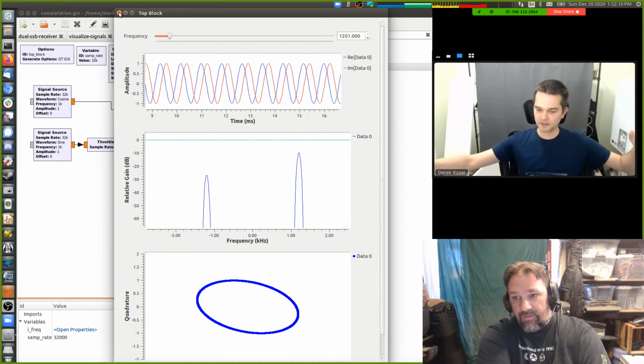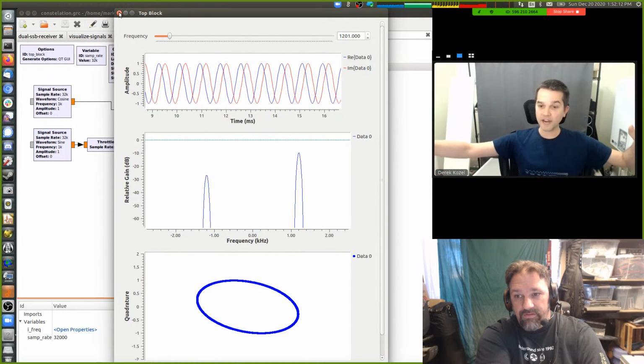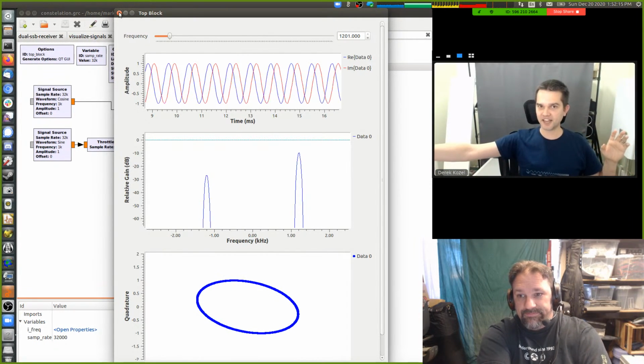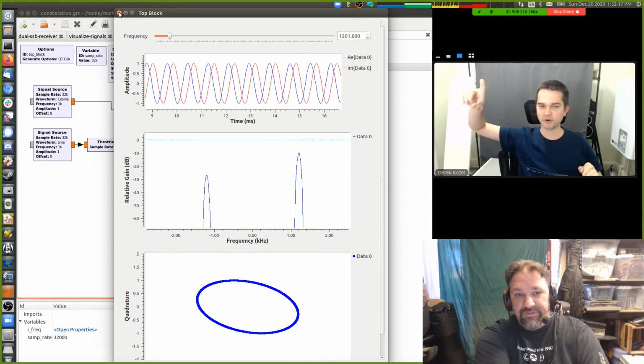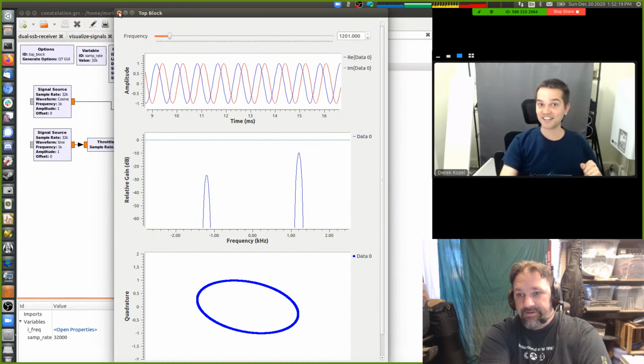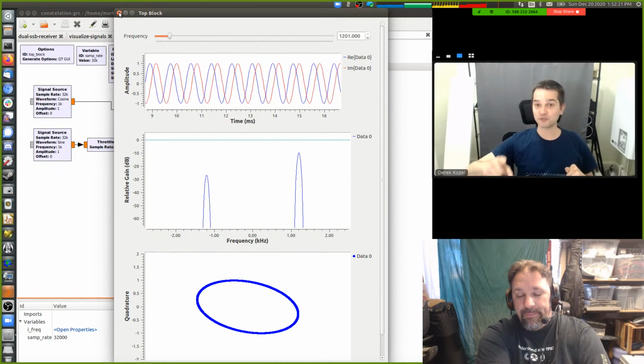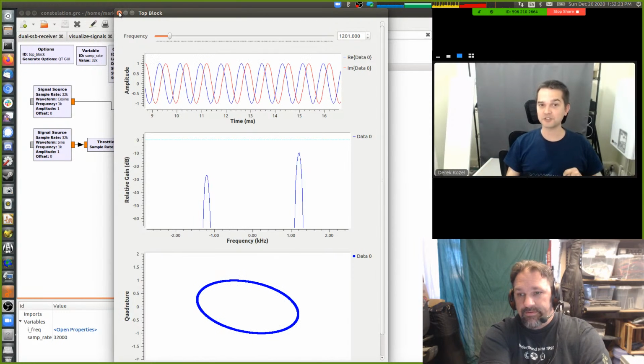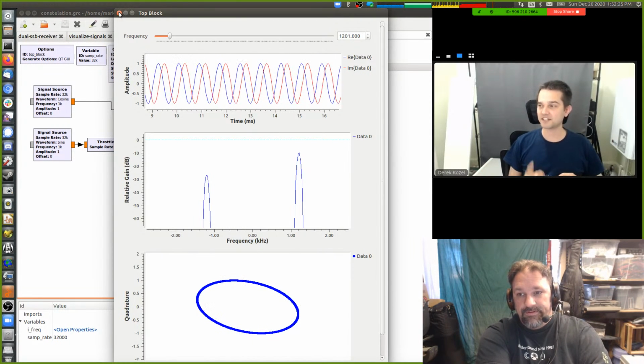But what frequency is it doing the filtering at? And I think this may be the interesting point. The first IF. The first IF, yes, okay. So at the first IF, you do get a double sideband signal. Yes.